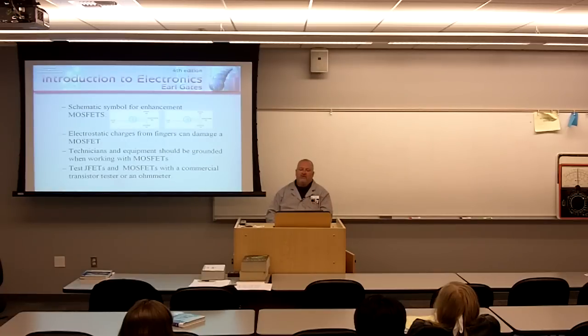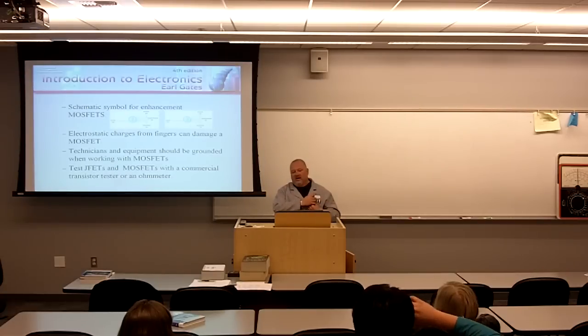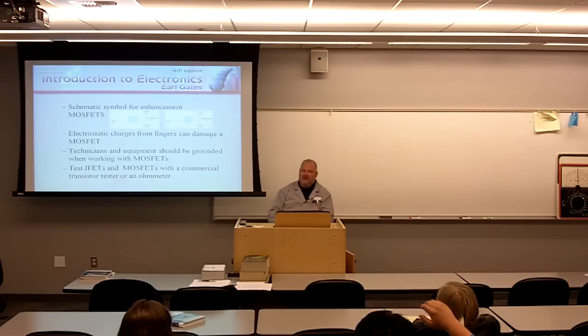Electrostatic charges from fingers can damage a MOSFET. Make sure you use all ESD protocols. Technicians and equipment should be grounded when working with MOSFETs. Test JFETs and MOSFETs with a commercial transistor tester or an ohm meter. Of course, you will not have the opportunity to use the commercial tester here at Lake Washington Technical College because Peter Welty and I believe it promotes laziness.